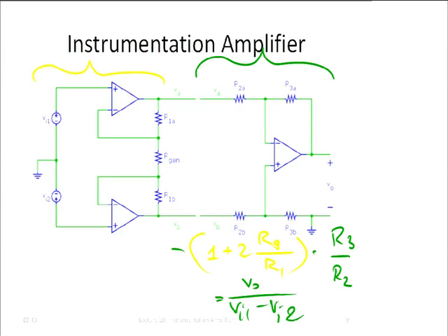But if you make the connections the way I showed here, then it is inverting. Also, another thing: generally these resistors, R1, R2, and R3, are actually hardwired into the circuit. They're already on the chip that you're buying, and the only thing you have to do is externally supply this resistor R gain, and there we can set the gain anywhere between 1 and 100 or something like that.